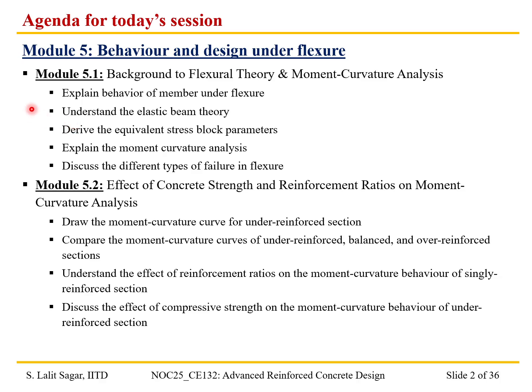Specifically, we tried to understand the behavior of reinforced concrete members in flexure. Then we tried to derive the governing equations based on the elastic beam theory. Then we derived the equivalent stress block parameters in order to determine the moment capacity and the curvature corresponding to the different levels of concrete, right? And then we explained what is essentially the moment curvature analysis.